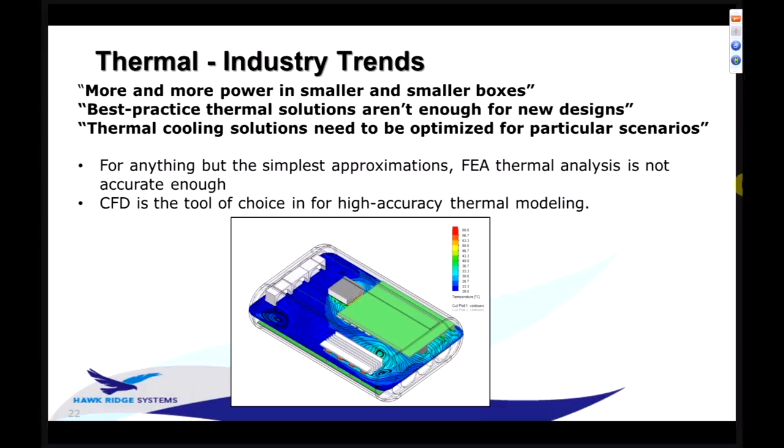What we continually hear is that more and more electrical power is being put into smaller boxes. Because of that, just a best guess at a thermal solution is not enough anymore. Thermal cooling solutions really need to be optimized for each situation they're going in: heat sink choice, heat sink position, any fans that are used. So it really leads to CFD for a lot of this.